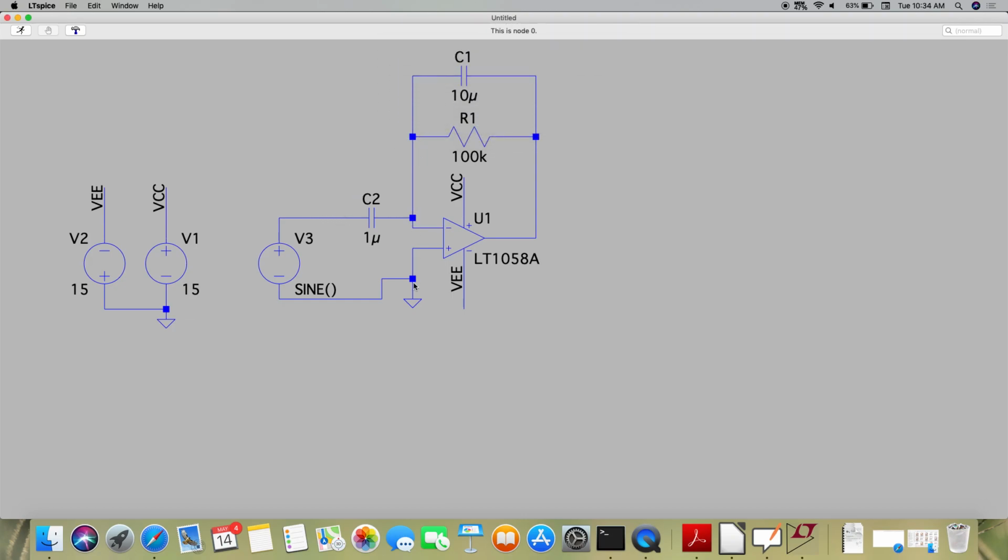Let's say this point, I know that it's 0 volt, but whether it's 0 volt or not, if I want to do the analysis, it has to be annotated on the schematic itself. So those kinds of analysis, we are going to call DC analysis, and that is the first analysis people are going to do if they are making some amplifier circuit, or using a BJT.